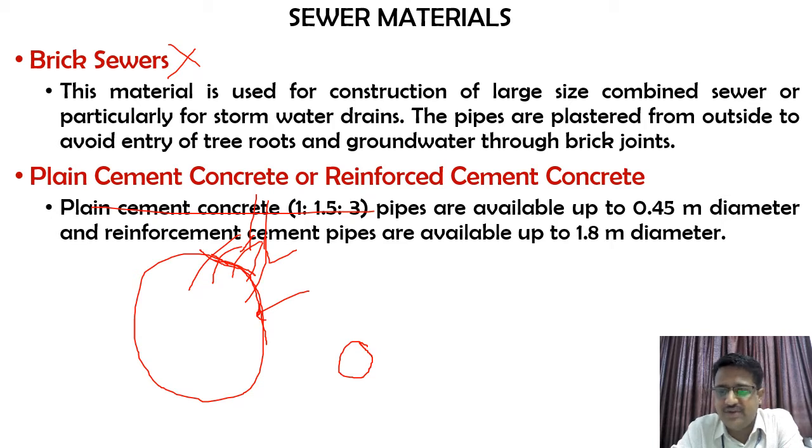One care that should be taken here is that there should not be much leakage, since brick is susceptible to absorption, so proper precaution needs to be taken. And most of the time it will be used for storm water drains, that is for runoff water. In runoff water, as I said, there will not be many impurities, so only that water will get absorbed basically.